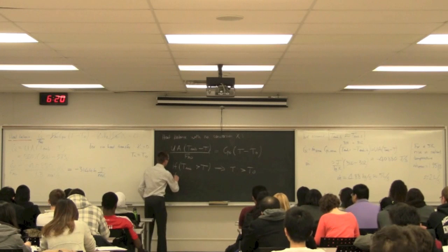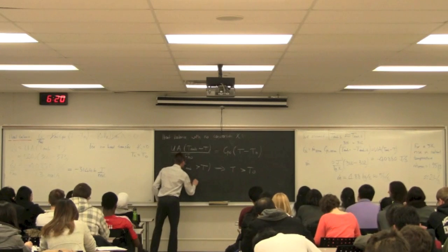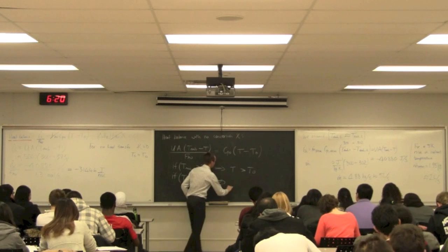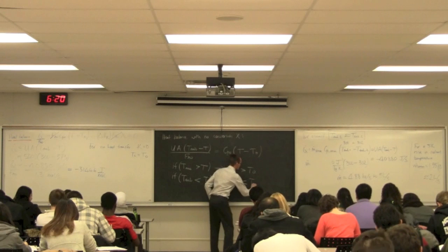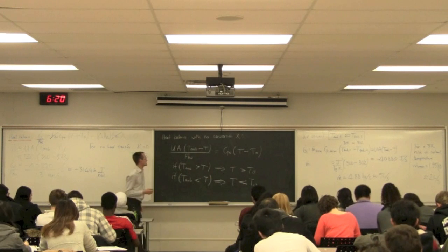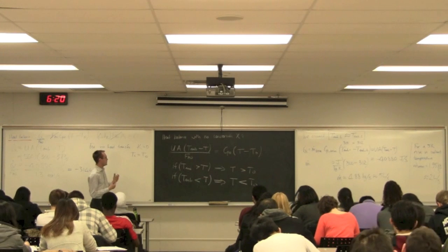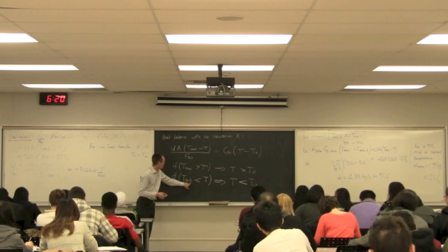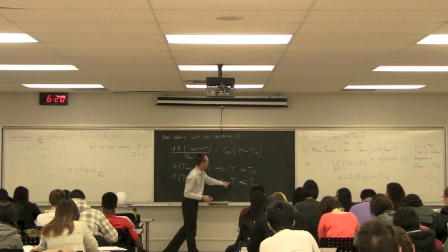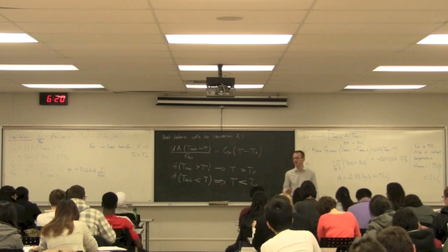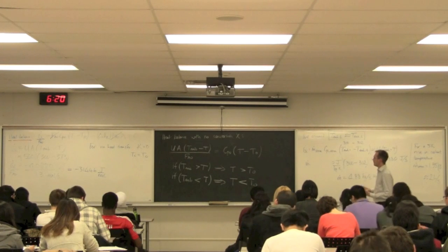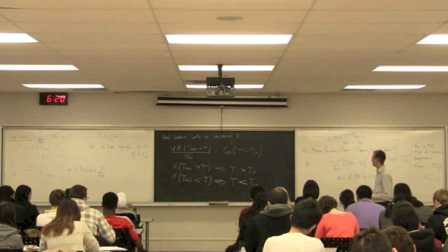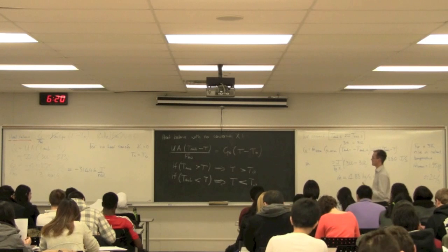Again, let's flip this around. If my coolant is now actually a coolant, so it's lower than the tank temperature, that implies my temperature leaving must be lower than my inlet temperature. Again, that makes sense. If we've got no reaction occurring, no heat being released or generated by reaction, if the temperature of my jacket is lower than the tank temperature, it implies my temperature leaving must be lower than the inlet temperature. So always explore your equations like this and make sure they match up with what your expectations are from an engineering perspective.